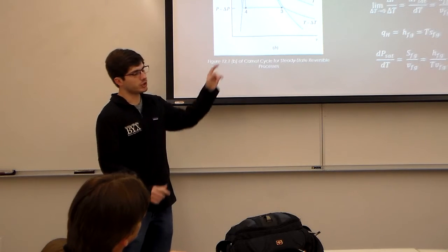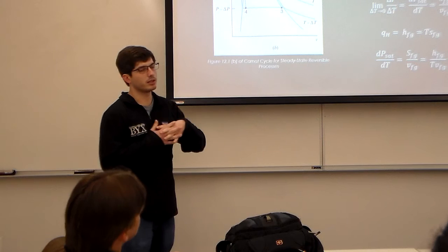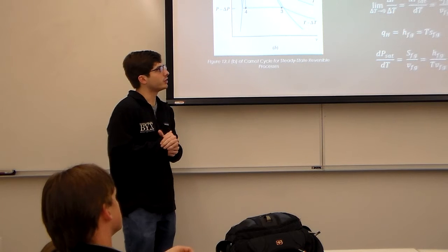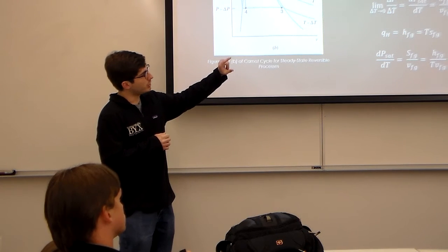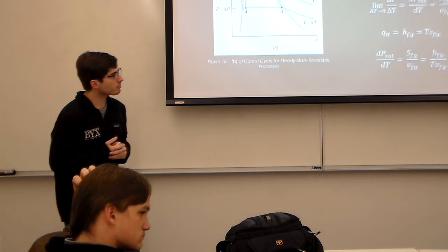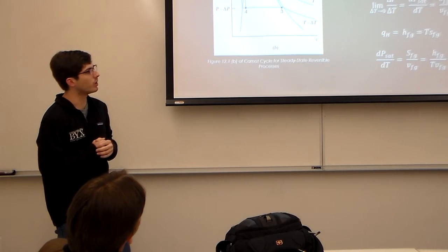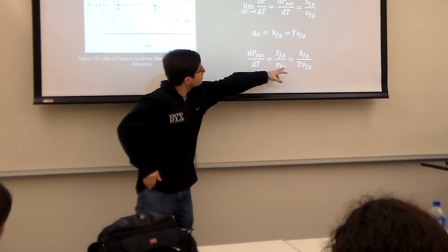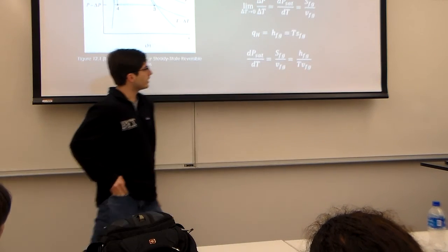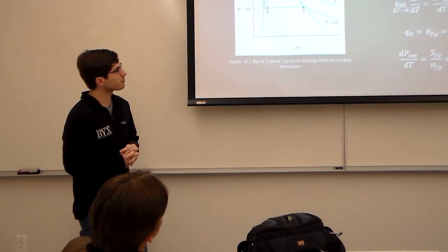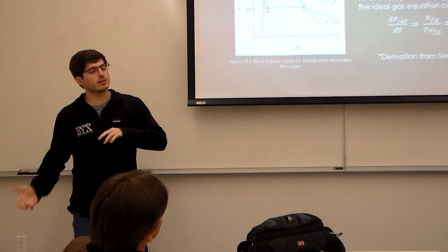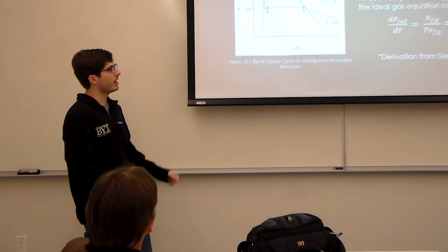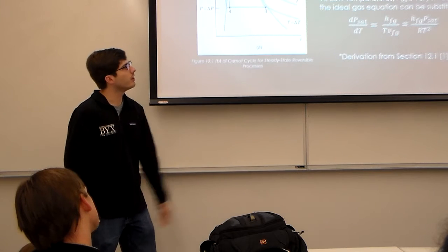When we take the two equations that we looked at with temperature and delta P, and we take the limit as delta T approaches 0, we get our difference in saturated pressure and temperature, and we get the relationship between the two inside the vapor dome. Since temperature and pressure are constant between 1 and 2, we can substitute in this fg value and get closer to the equation we'll be using. Next slide. Then taking the ideal gas law, we can substitute in for that specific volume and get rid of it, and we'll have the actual equation we'll be using for the experiment.